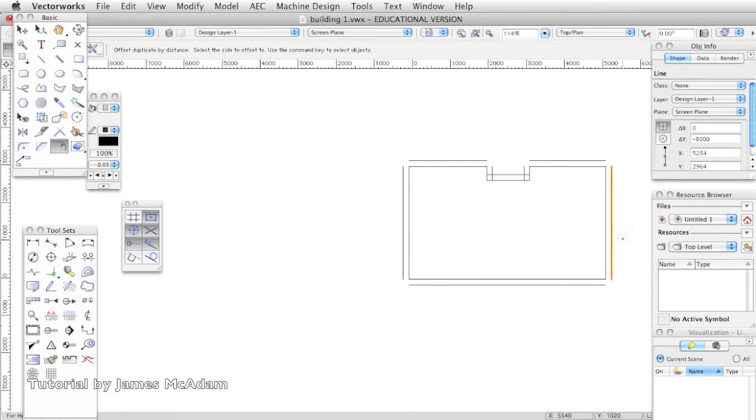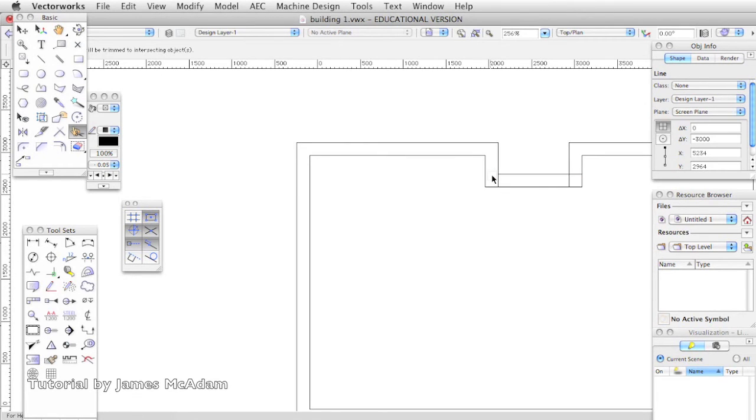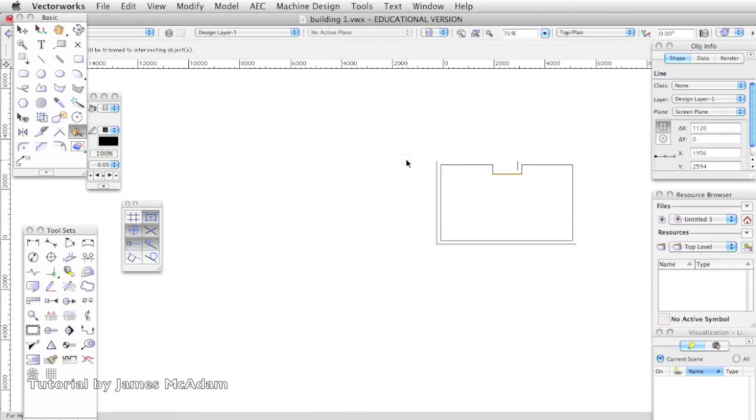And now I'm going to make these lines join up by using the extend and connect tool. So if I click one line to the other line, click OK, and it's actually joining both lines to one another. So it's a really quick way of extending the lines. Okay, and now I just need to trim. So I'm using the little button which is like a hand and scissors, clicking the side I don't want to keep there, and it deletes it. Okay.